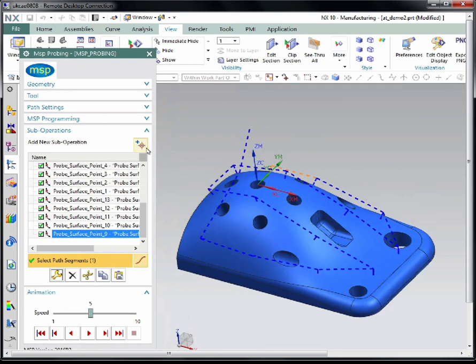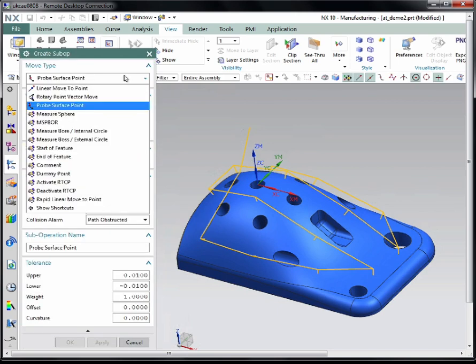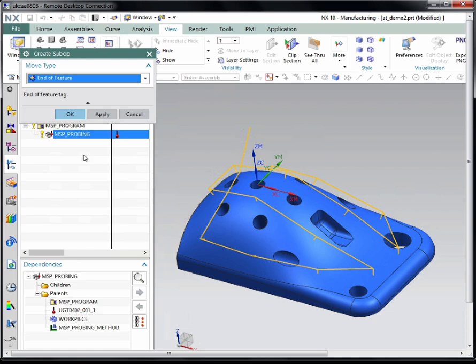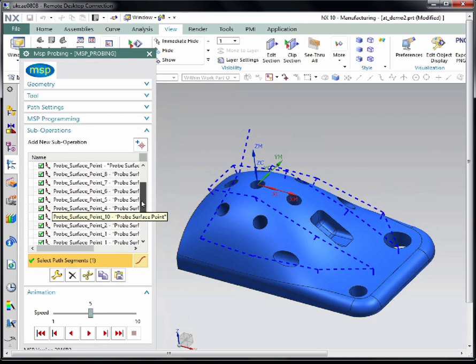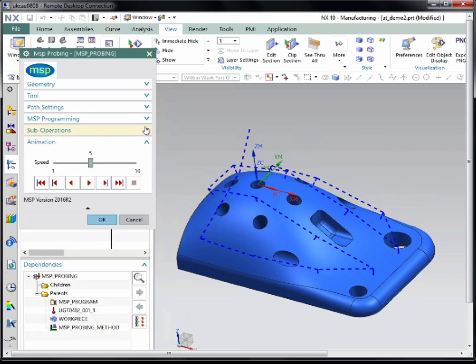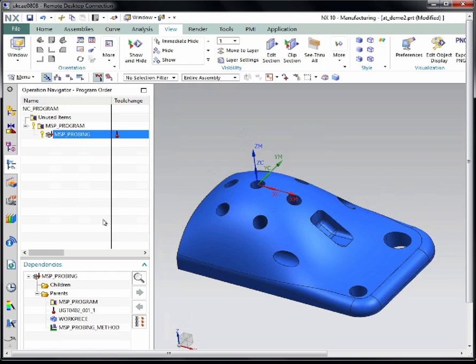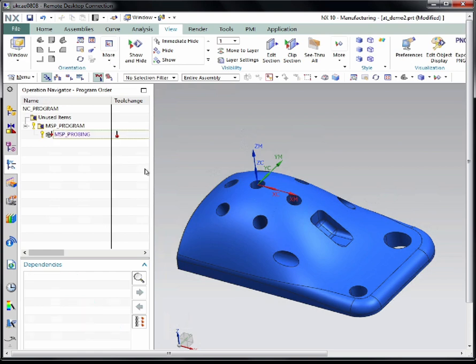You must remember to close off the feature if you have started a feature. So, end a feature. I'll just close off the last feature that was opened. So in this case, it is the point group. And if I just select OK to that, that is the end of my alignment process. When you finish a process, it's always good to save. I'm not a fan of losing work because I haven't saved regularly.